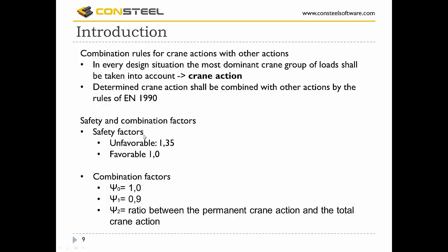The safety factor in unfavorable situation is 1.35, in favorable situation is 1. The combination factors are 1 and 1.5, or the ratio between the permanent crane action and the total crane action.